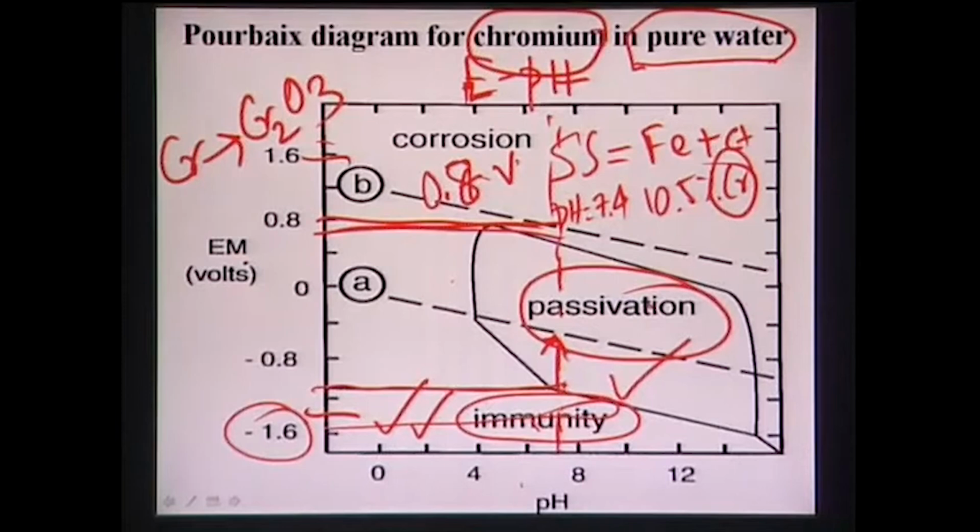And again it may be so that your passivity region is reduced or contracted, and therefore with a simple increase above 0 volt, the material can go to the corrosion region. Okay? So in that kind of SBF environment or in vivo environment, this particular diagram will not be valid anymore, and you need to construct a separate diagram by conducting tests in the pure SBF environment, or a simulated body solution which will simulate very closely the in vivo environment.